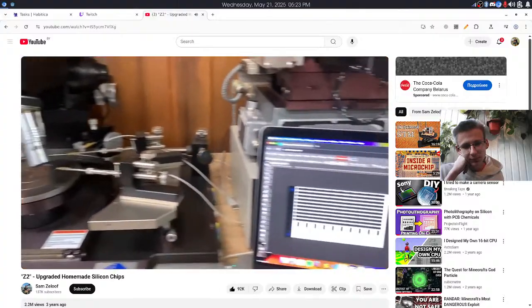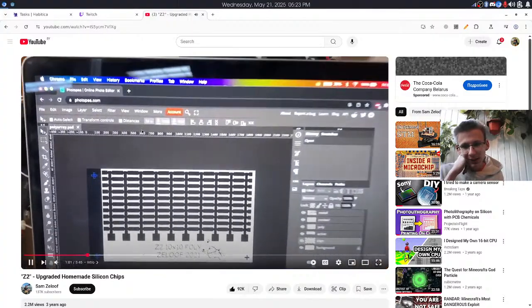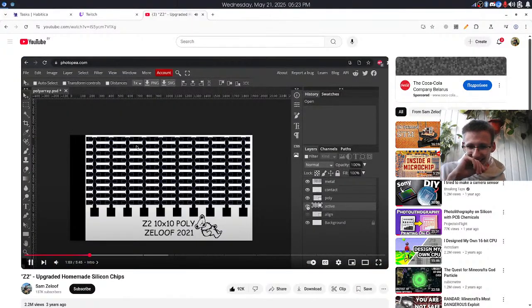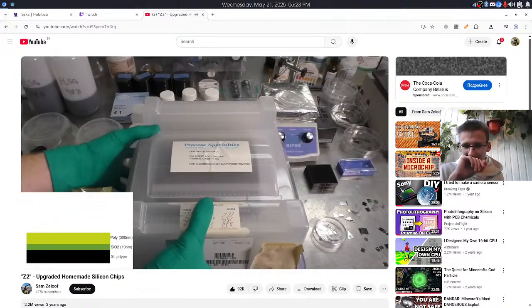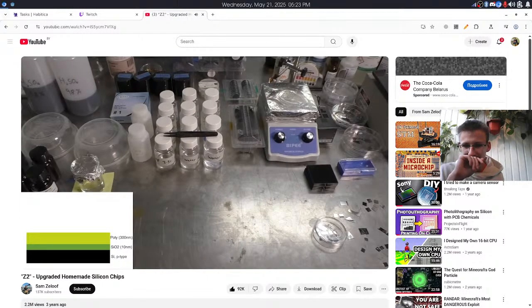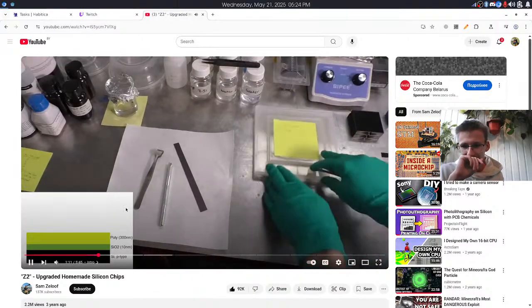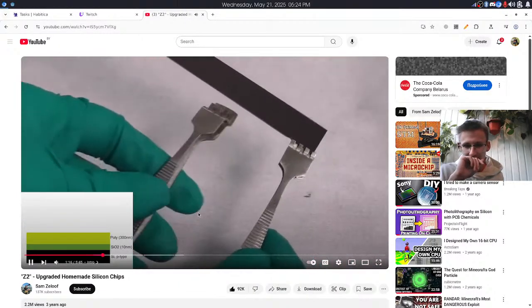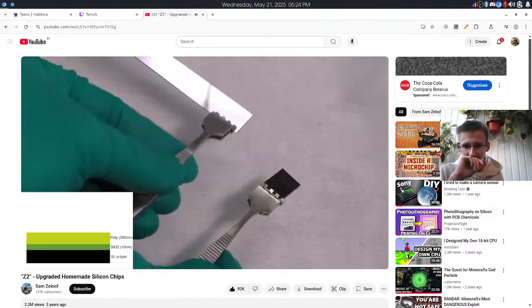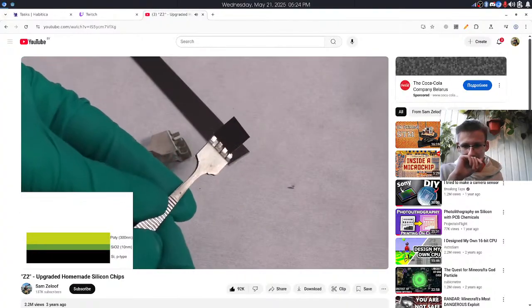For simple chips like this, the process actually starts in Photoshop. There are only 4 chip layers, and for simple chip design it's easier to use this than some more complicated software. I start with a lot of 200mm wafers that have some pretty specific starting parameters. They're way too big, so I dice them up using a diamond scribe into smaller bits. I normally do about half-inch squares like this, but I can process larger things up to about 2-inch wafers.